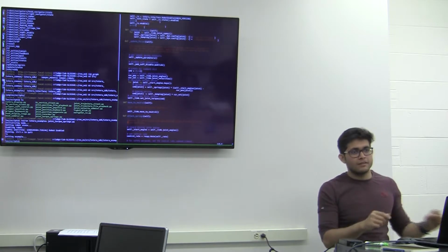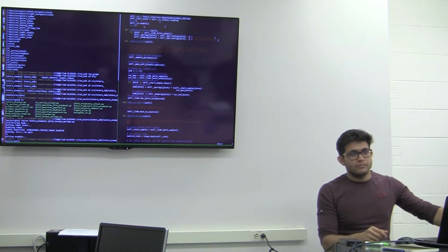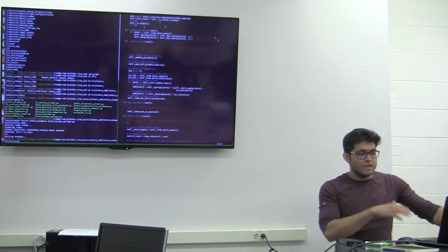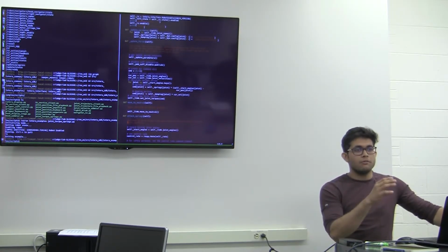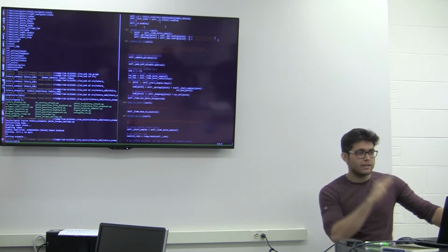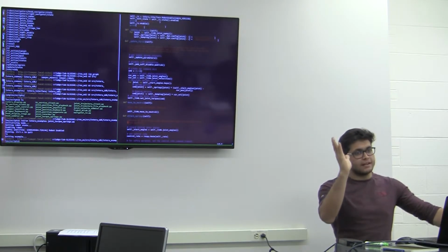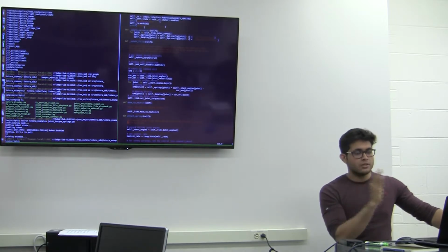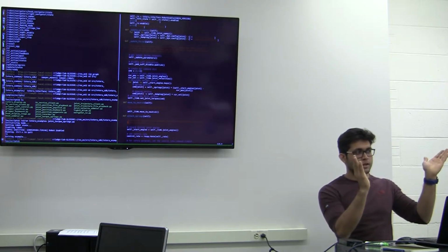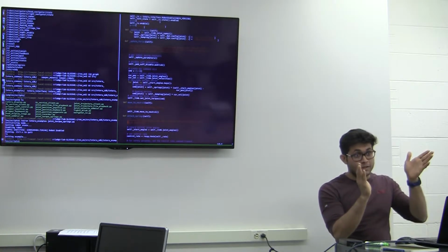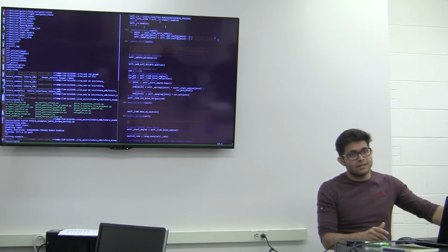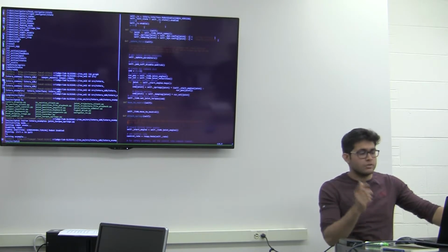Which means you will not be able to do the joint tasks, is that what you're trying to say? You can do that. Again, you will be able to go into that. But for basic functions like this one, you see it always saves two angles, initial, final, initial, final. So that's how it works. It takes a reference value and moves from there. So it knows this is my home position, this is my other one, and there might be a singularity in between, but I don't care because it will solve it itself. It knows that there is a singularity there, so it won't go into that area.